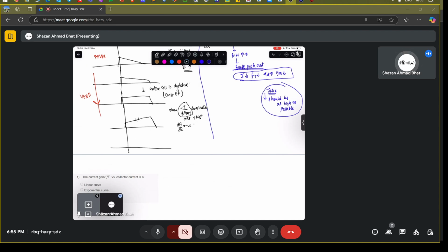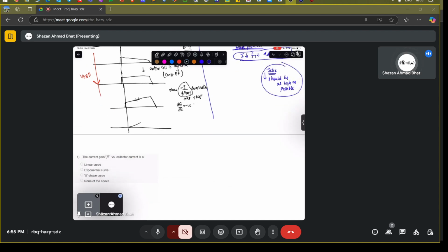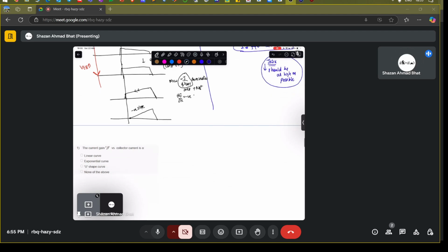Now you go on increasing it further. You see that this particular point shifts here and you have an electric field profile like this, which has a negative slope. So at a point in here there is zero field at the base-collector junction. What does it do? It spills holes to the collector. This is called base push out. The base pushes out the holes to the collector, and it is detrimental because it reduces the gain and it affects the delays and other things.